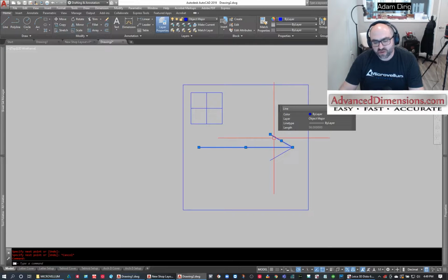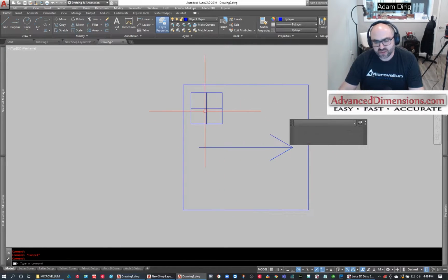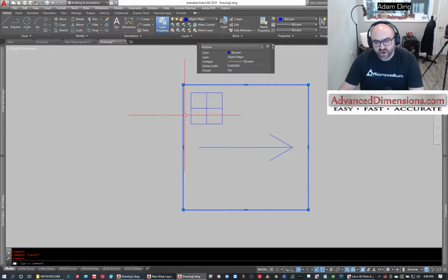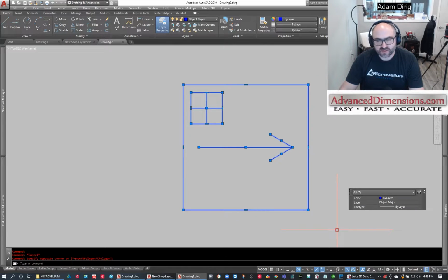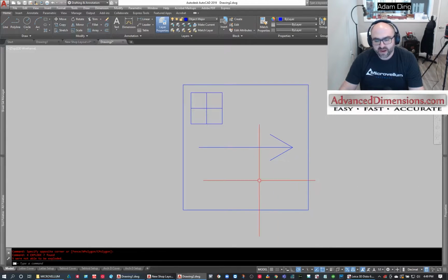Before we start the thought of making this a projection file, we have some things to do here. First, we can have no rectangles in this projection file. These are just going to be lines. So I'm going to grab everything that I just drew and hit X for explode, and I'm going to explode them. So all I am looking at are lines. That is key. That's key for this stuff to show up.